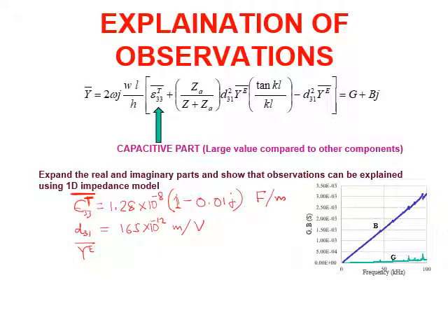The bar indicates that it's dynamic in nature, and the E superscript indicates that this is measured under zero electric field conditions. This is 6.41 into 10 power 10, (1 plus eta j). The unit is Newton per meter square or Pascal. We have already discussed why we have positive here and negative here. This we discussed in the previous class.